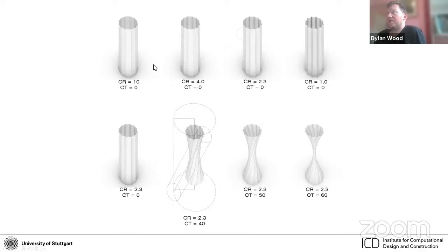On the top, you can see how we're able to create this curved or corrugated surface active structure, which works specifically well with these high curvature thin sheets. On the bottom, by slightly twisting this, or slightly shifting the angle of each of the single curved geometries and then intersecting them, we're able to create an overall double curved geometry that works even better in terms of surface action.